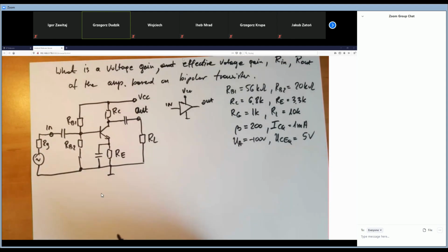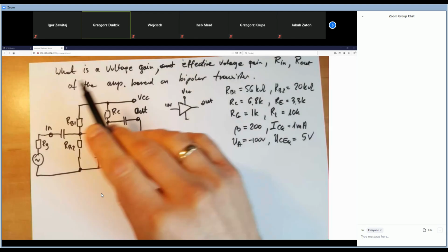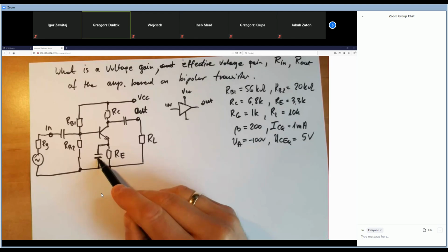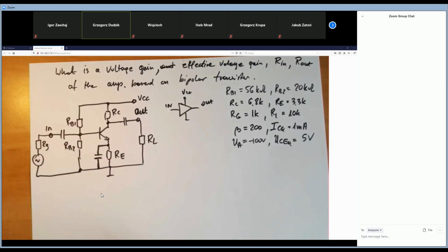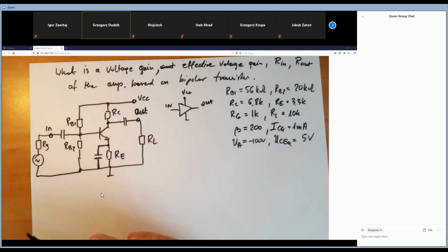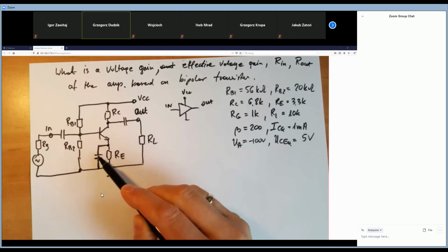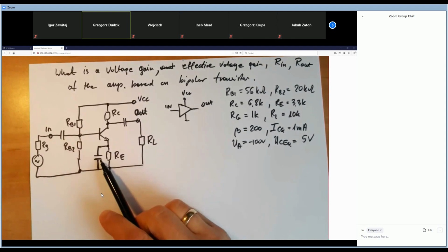Why, in the voltage amplifiers, is the emitter resistor, which is used to thermally stabilize the amplifier, paralleled with a capacitor of a huge value? Because this capacitor has no influence on the DC analysis, since the DC signal does not pass through it. This is a capacitor, of course, but with a huge capacitance.